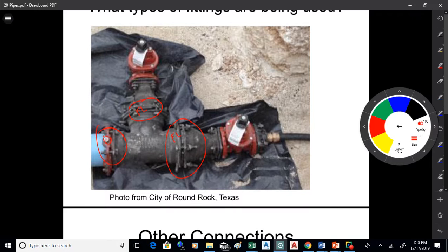That is a little bit unusual to use those with a plastic pipe. That looks to be that C900 here. That's a little unusual to use a set screw like that on a plastic pipe because you could break it, but you know, hard to say there. They might have just put that together just to show how they're doing it. I don't know. Okay, so that's a mechanical joint there. So that's how those fittings are being used. You also see some reducers there that look to be flange by flange, and then they're going to the valves after that. So that's how they're doing this connection. You know, it just depends on the situation.